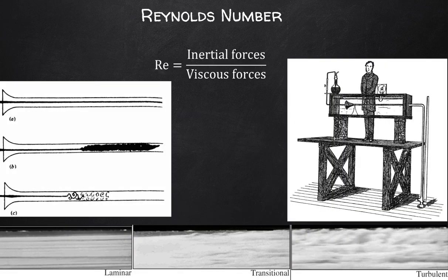Another dimensionless number which we have been discussing throughout the semester and last semester is the Reynolds number, which describes the ratio of the inertial forces to the viscous forces of the fluids. So it involves things like the viscosity, the velocity, the hydraulic diameter, as well as the density, of course, which will also have an effect on the inertia of the fluid.